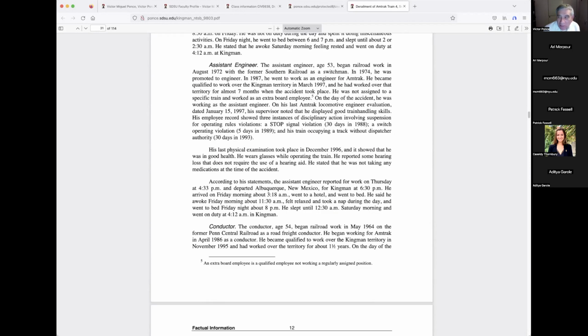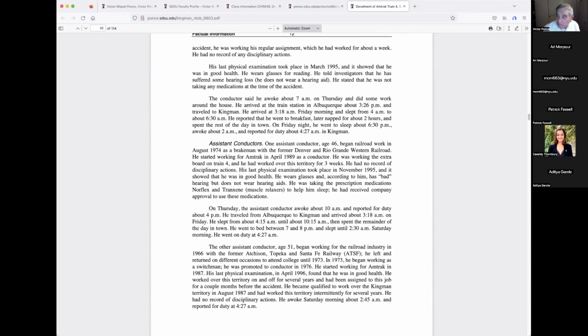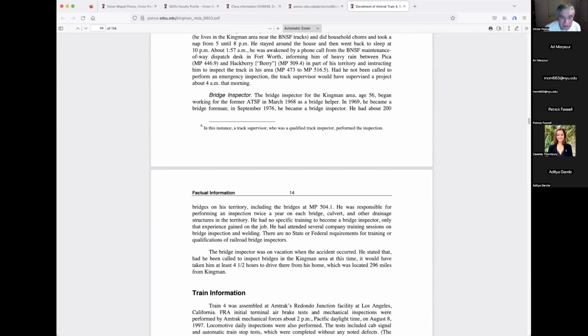So in summary, what happened here? Old bridge, more than 100 years old. It was repaired here and there, but not totally, completely repaired. And it failed because the piles were at a certain depth, and the local scour was large enough to undermine the foundation. And on top of that, there was a wall on the side, and that wall also failed, because we see the wall on the floor of the creek.